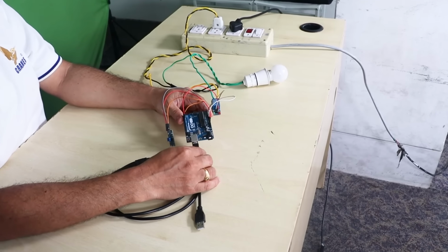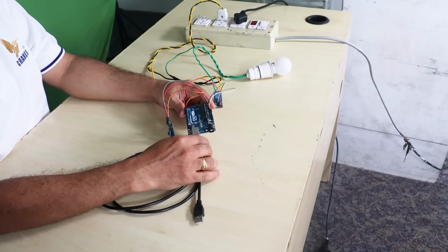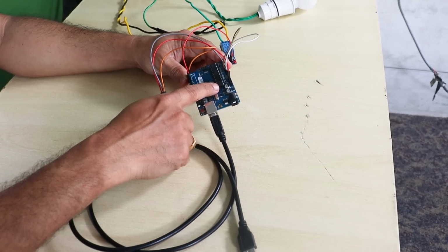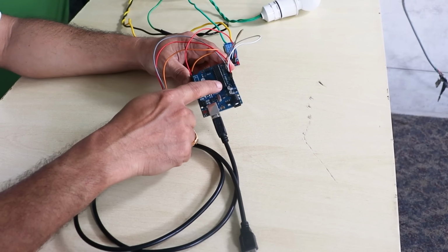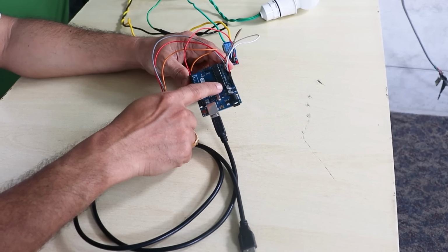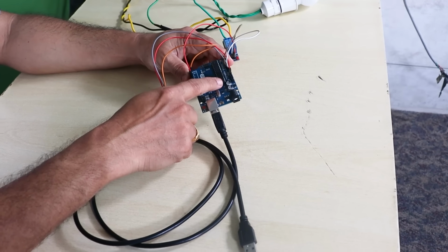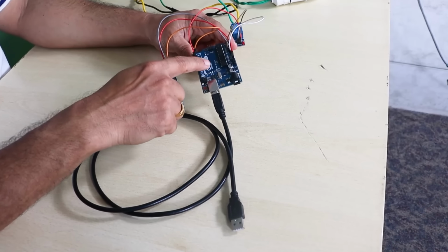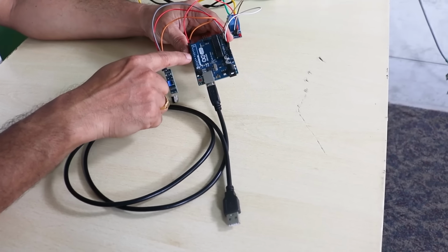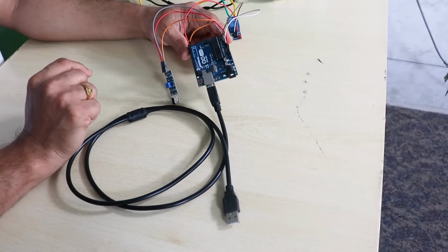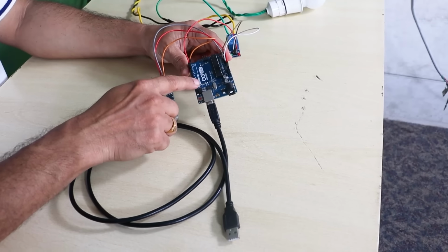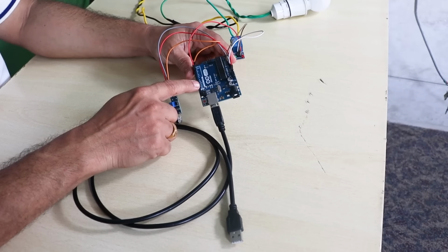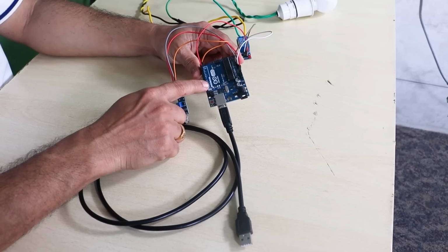This is our Arduino UNO board. This Arduino UNO board has a microcontroller, the ATmega328P. It is an 8-bit AVR microcontroller. It has 16 MHz of clock frequency, and it can stretch up to 20 MHz clock frequency also. You can see there are many GPIO lines here. This Arduino UNO board has 13 digital GPIO pins plus analog pins, and it supports pulse width modulation as well as UART. It also has SPI and I2C support as well.